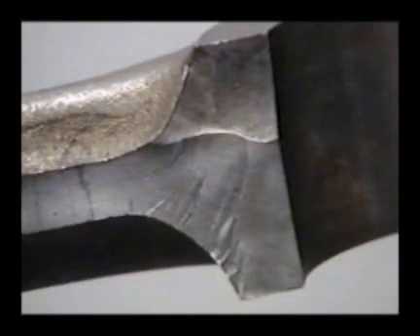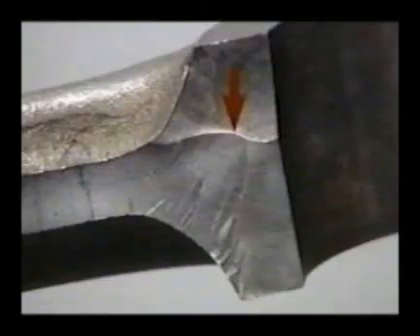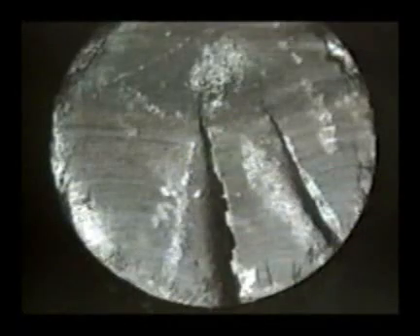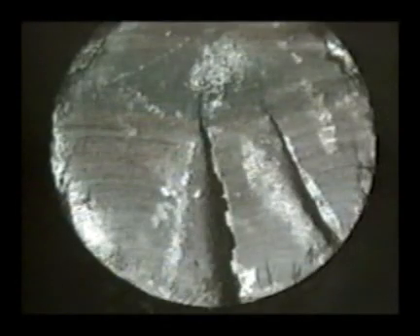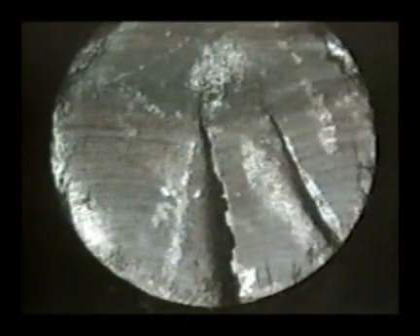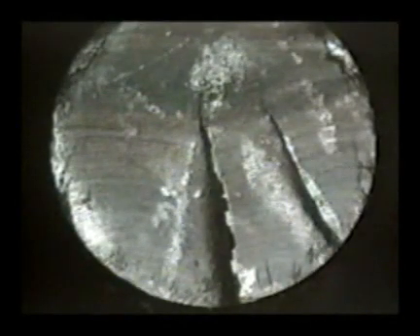Fatigue cracks start where ratchet marks and beach marks start. Just above center, we see a distinct line where ratchet marks and beach marks begin. This tells us the initiation site is not at the surface, but deep inside the part. Ratchet marks like these that start at the surface indicate fatigue cracking initiated on several different levels along the lower edge. Can you identify what type of fracture this is and where it started?